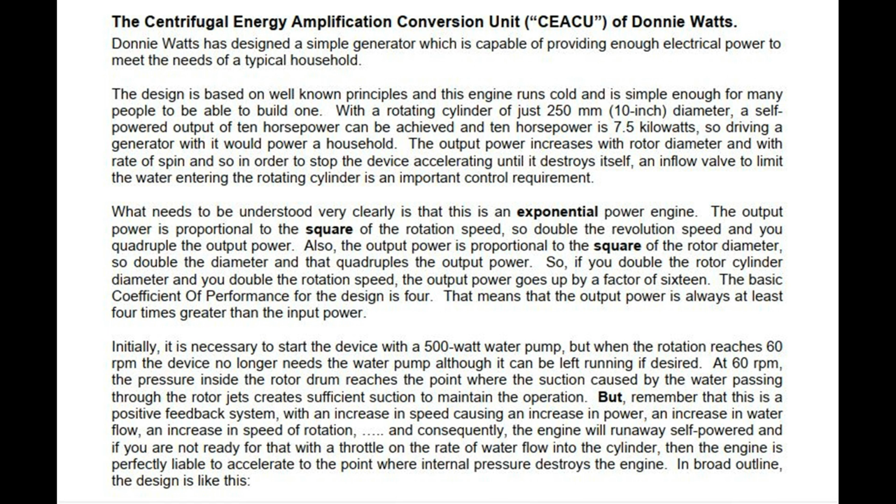And consequently, the engine will run away self-powered, and if you are not ready for that with a throttle on the rate of water flow into the cylinder, then the engine is perfectly liable to accelerate to the point where internal pressure destroys the engine. In broad outline, the design is like this.